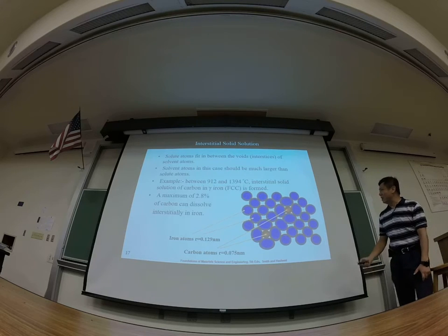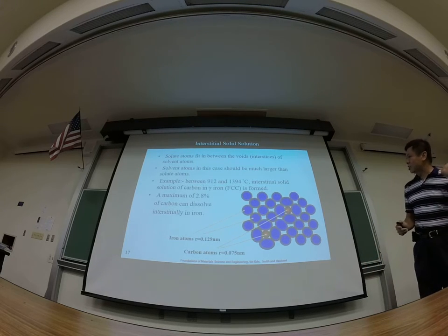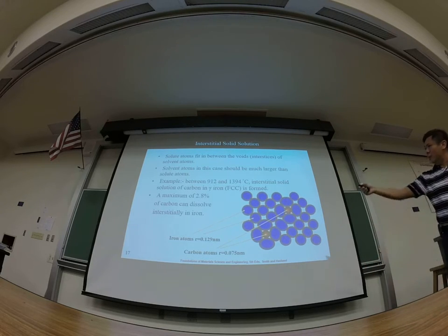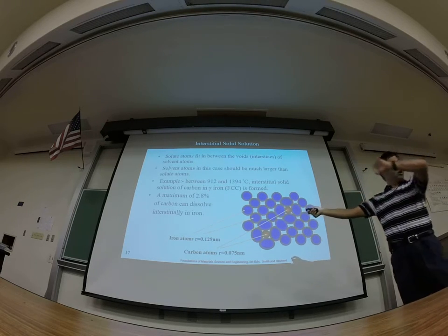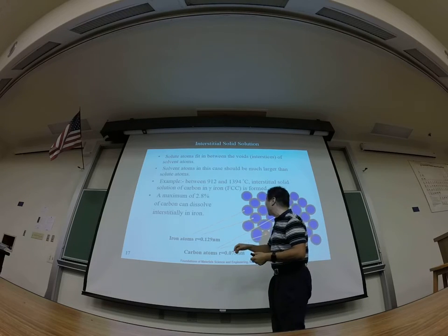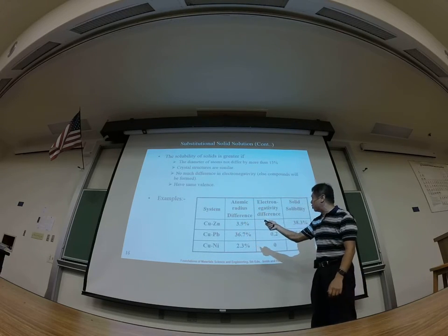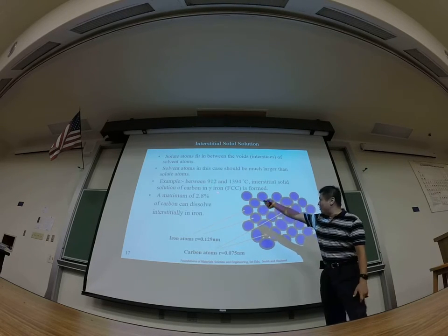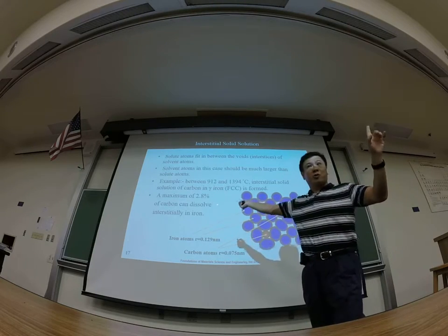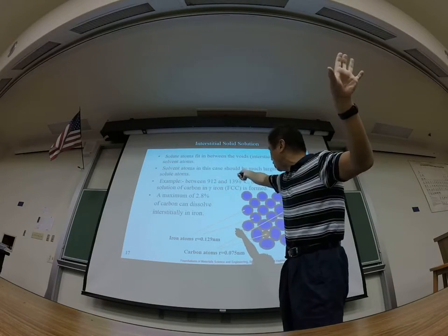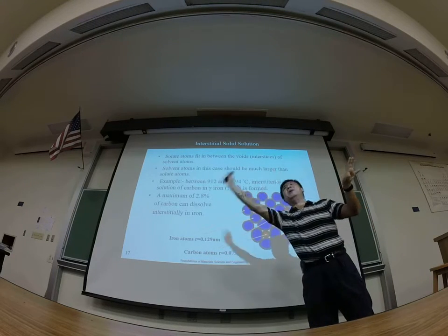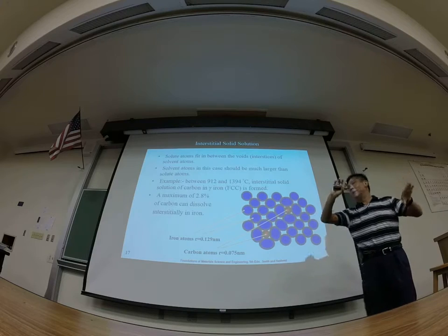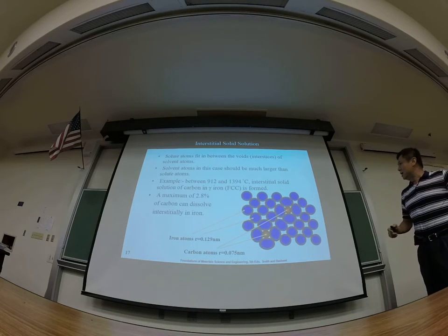Okay, so usually we need a very large difference. One widely used example is gamma iron. When we talked about chapter 3, we know that in a special temperature range iron will be in the FCC structure. Below that temperature, it will be BCC. Above this temperature, it will be in another BCC state. We call them alpha, beta, gamma iron, right?